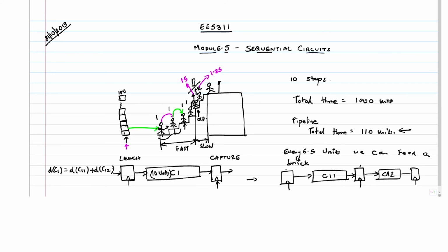And hence, what is the maximum operating frequency of this pipeline system now, or maximum time period? Just go by the analogy that we just gave. In general, I am asking. Yeah, it's basically determined by whichever has higher delay, that is going to set your clock frequency, right? So therefore, if I have a clock period like this, if I have a clock like this,